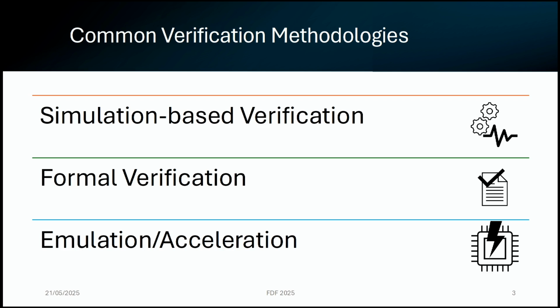If I had to compare formal verification with simulation-based verification, they are very different in the way in which you can use them. Simulation will allow you to explore a specific part of the state space of your design, basically, and those are the tests that you're writing. Formal verification will try to formally prove your design mathematically. This is not always possible, unfortunately. Otherwise, we would blindly go and use formal verification the whole time. But it's pretty good at exploring the first stages of the state space.